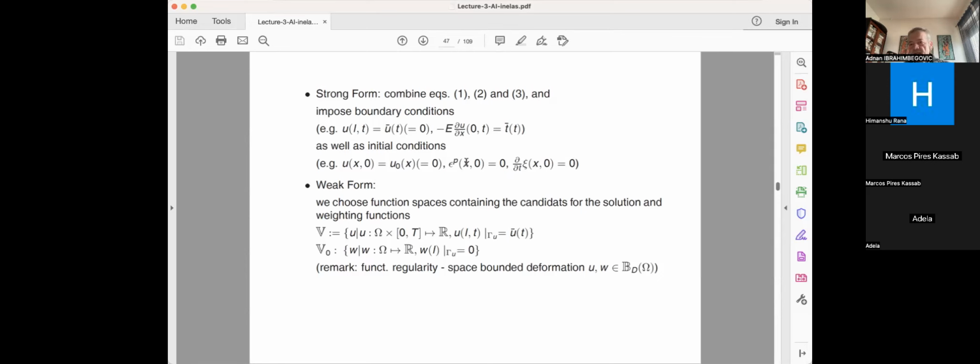And I would just start from the initial condition, then carry on my computation. But here, to make it simple, we keep it like there's no initial condition at all. Then I will follow the path of the finite element solution scheme. In other words, I'll get my representation of the displacement field by using the finite element interpolation function NA, and I'll have